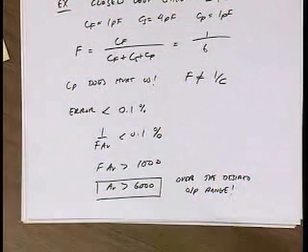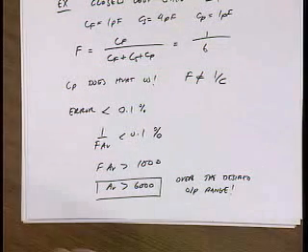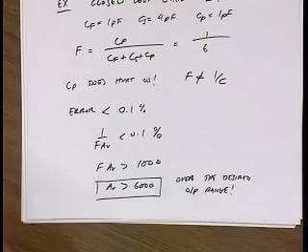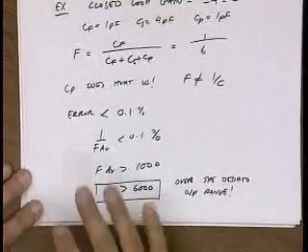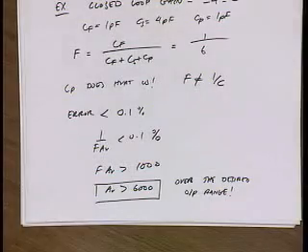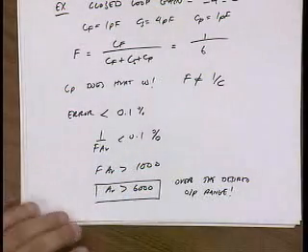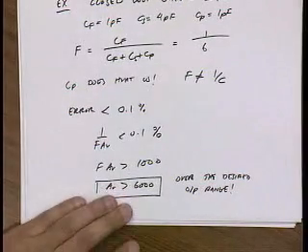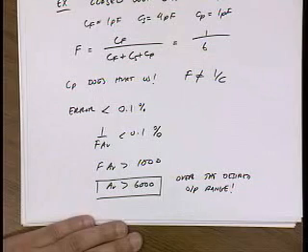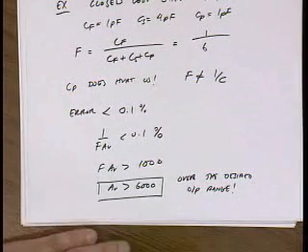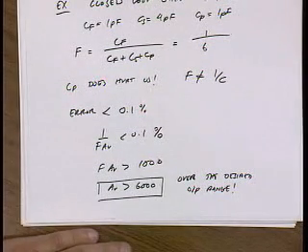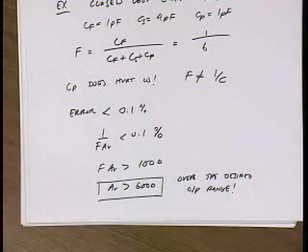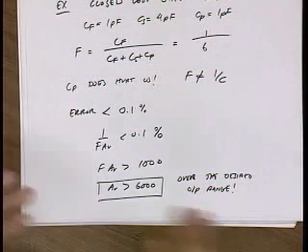So now you get to see why this output swing is so important, and specifically why the gain over that output swing is very important. If I were speccing this amplifier and giving it to you to design, I would say, I need a 1 volt swing at the output, and over that swing you've got to give me a gain of 6,000 because I need to hit the 0.1% static error specification. Then you design your op amp and plot its large signal gain as you vary the output voltage.